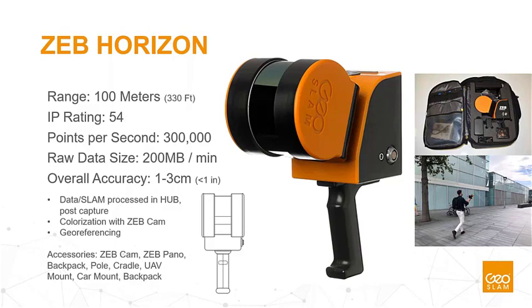Another notable difference is that with this sensor, we are capturing intensity value. That's basically the material return on the data points that we're collecting, so you can actually see variations in materials. A good example of this is road lines on a road. You'd be able to see these really easily with this system, which is not the case with our Revo system. That's not capturing intensity value.